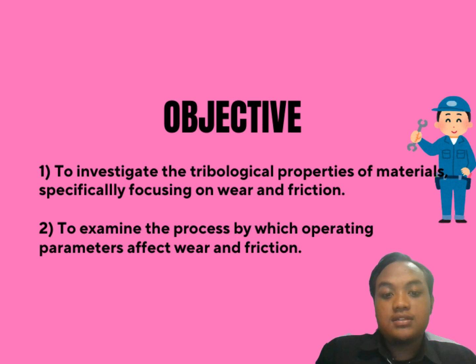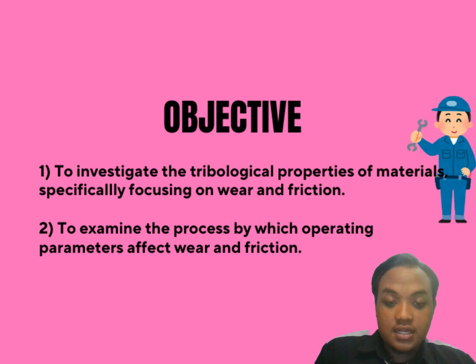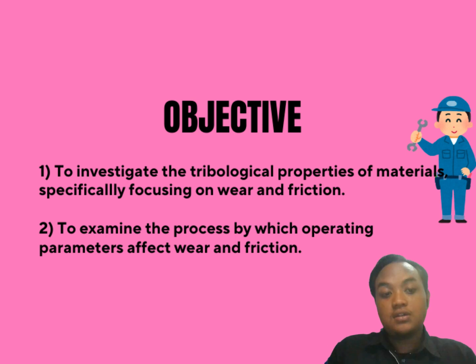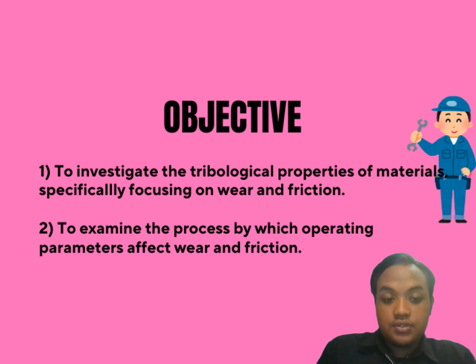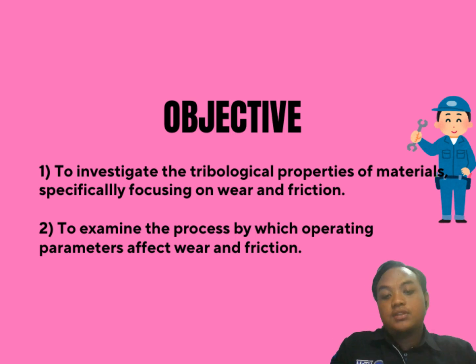Next, understanding wear mechanism. Analyze the wear debris and surface morphology to understand the underlying wear mechanism, such as adhesive, abrasive, or corrosive wear. And for the last one, testing under various conditions. Conduct tests under different loads, speeds, and environmental conditions, such as dry, lubricated, and high temperature, to simulate different operational environments. By achieving these objectives, the pin on disc test provides valuable data that can be used to improve material selection, surface engineering, and lubrication strategy in mechanical design and maintenance.